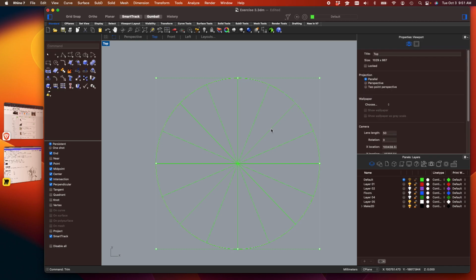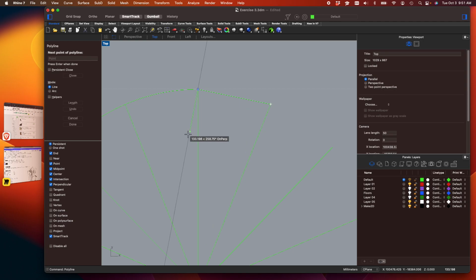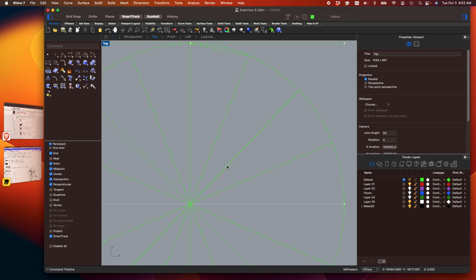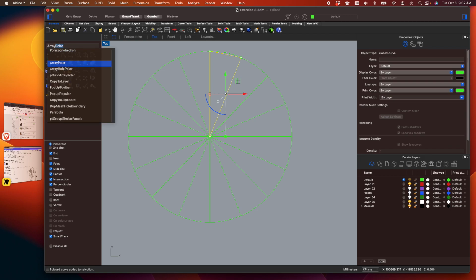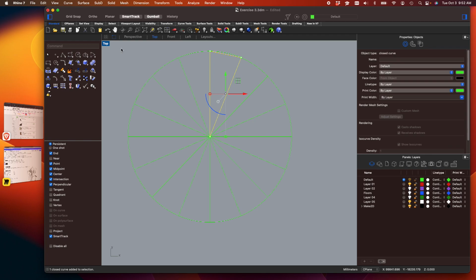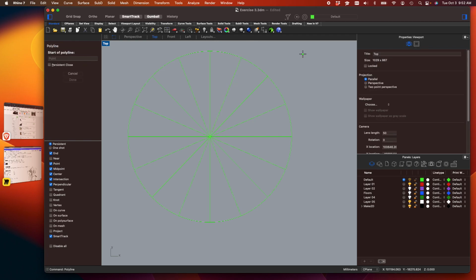Now, I could get fancier with it, but I'm going to kind of go for speed right now and just make one of those steps real quick. I'm going to just kind of go straight. That way these are all triangles. What's really nice is this is kind of just my template. I could copy that again a whole bunch of times, or I could do polar array, right? But in my case, I'm just going to make one at a time just to kind of show you what to do, right? Obviously, you want these steps to really overlap. So, in fact, you would make kind of 2 steps.